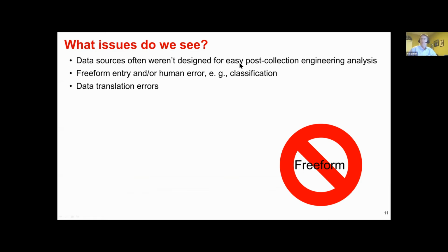So an example in the test space would be that when a tester is producing information, the most critical information that's coming off that tester is the binning information, because the binning information is going to drive all the downstream decision making about where the part goes. Does it get scrapped? Does it move on to the next test insertion? Is it a particular failure category that we need to track, and so we need to gather more information about that part, perhaps run it through some additional testing. But perhaps all the other additional parametric information that's coming off the tester maybe isn't as easy to get to in some cases as is something critical to business operations like binning information.